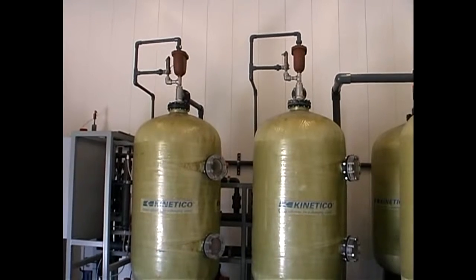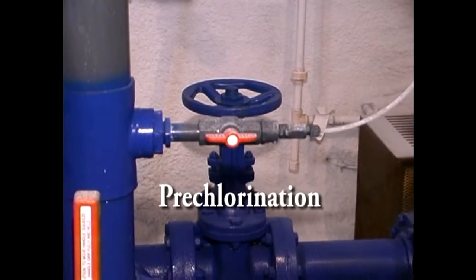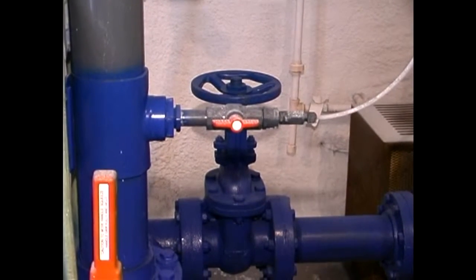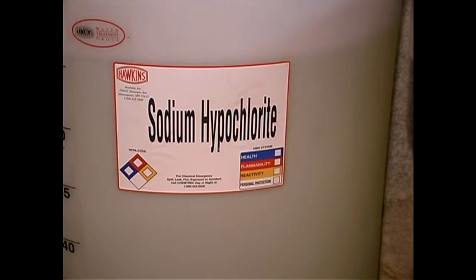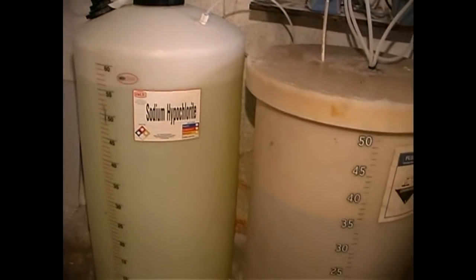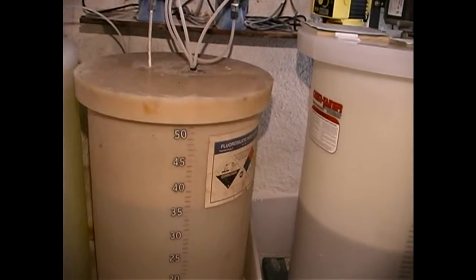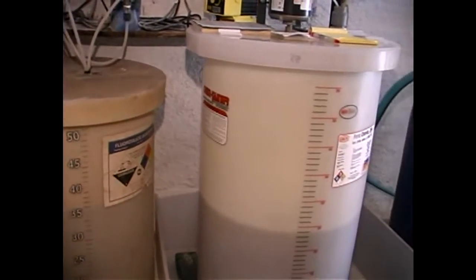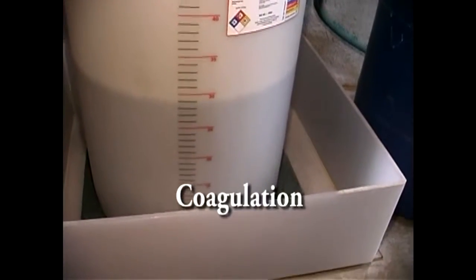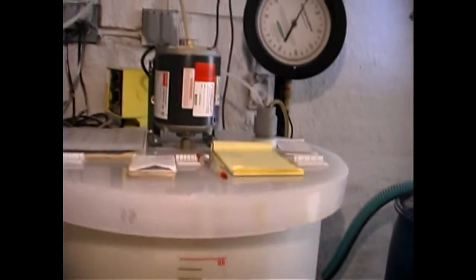The major components in the treatment process are pre-chlorination. The original gas chlorination system was replaced with a liquid chlorine feed system to improve the reliability and safety of the chlorination system. This converts the arsenic 3 to arsenic 5 and provides the oxidation of the natural and added iron. Coagulation. Ferric chloride is added to the water at a dose of 1.2 to 1.3 milligrams per liter.